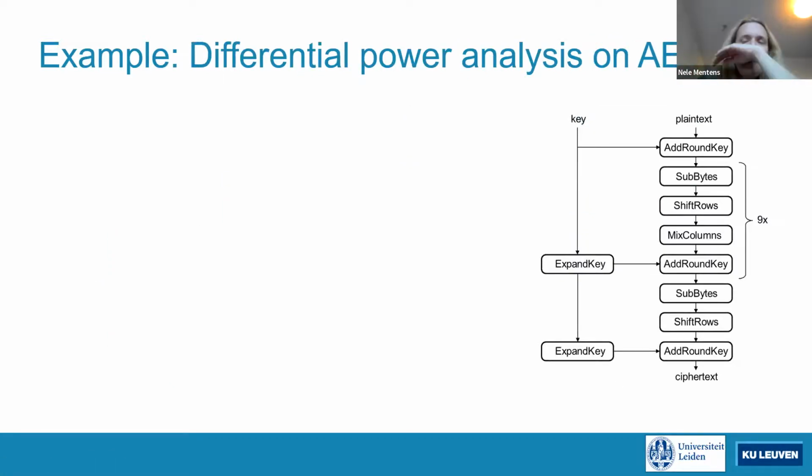In some algorithms, like the AES algorithm, which is shown here, there are no conditional branches like in RSA, which means that the operations are always time constant and you always execute the same sequence of operations. So AES looks like this. Plain text comes in. It's combined with the key through an XOR function. This is AES with a 128-bit key.